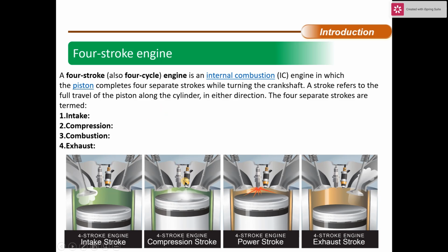Now the compression stroke. This stroke begins at BDC, just at the end of the suction stroke, and ends at TDC. In this stroke, the piston compresses the air-fuel mixture in preparation for ignition during the power stroke. Both intake and exhaust valves are closed during this stage.